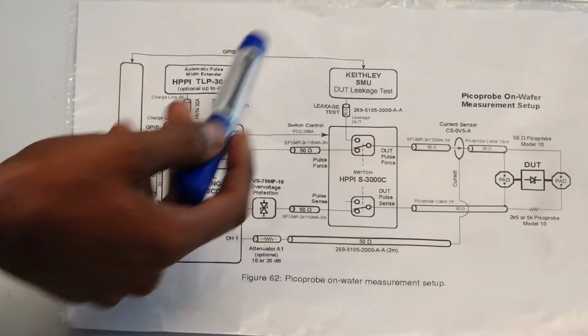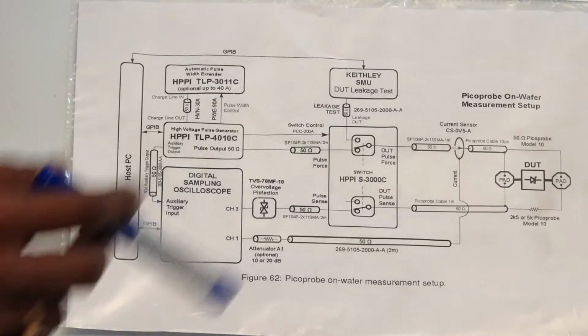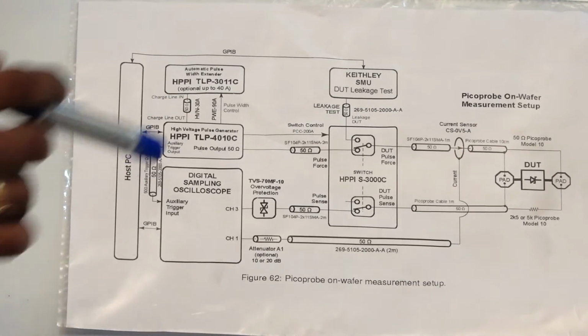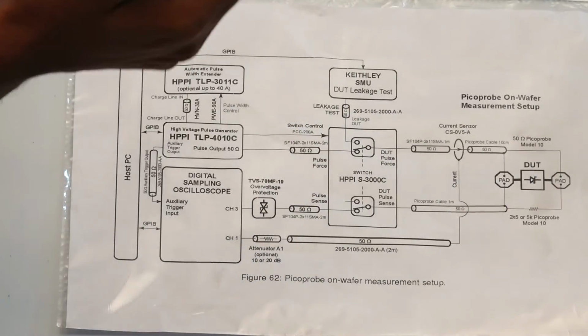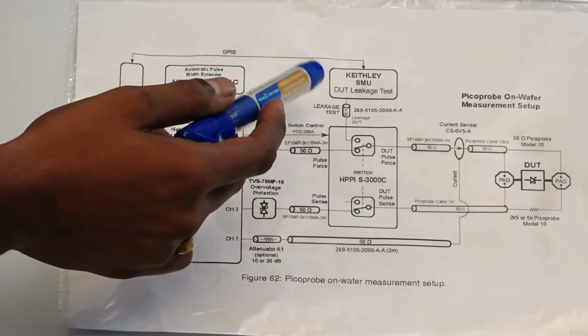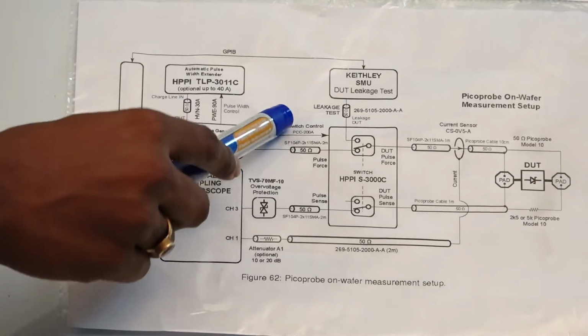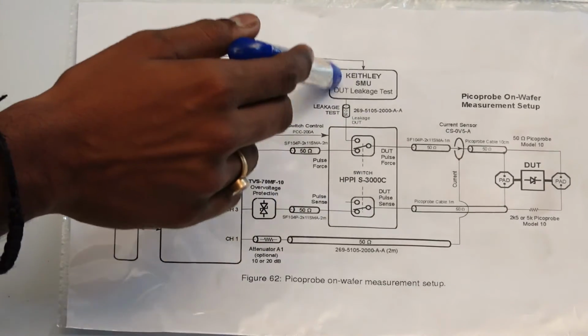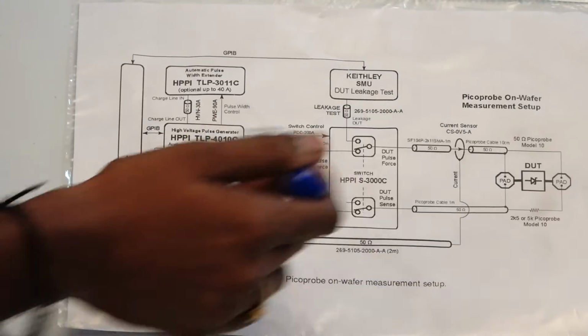Now I was talking about this SMU as well. As I told you, this is called leakage measurement. Leakage measurement is important because you would like to see how your device is getting shifted. So say for example, when the device was brand new, at a voltage application of 1 volt, it was passing say 1 nanoampere of current. You would like to see how the device current is shifting as you apply different stresses.